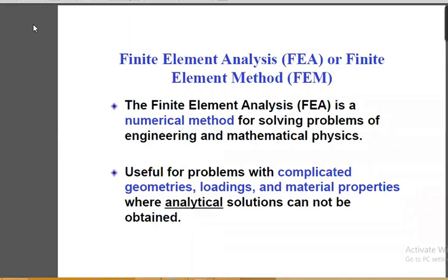So in all your topics or in all your units, there are some basic principles. By using these basic principles, you can find out various types of stresses, like tensile stresses, compressive stresses, bending stresses, or buckling stresses. This can be calculated based upon your basic principles. But in that case, you observe that your geometry is uniform. Uniform means the cross section of the geometry is uniform. Then and only then you can apply all these principles.